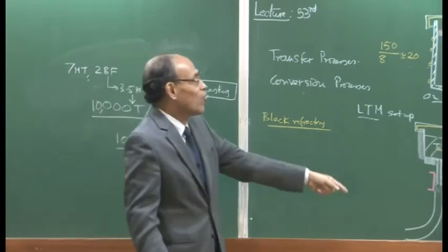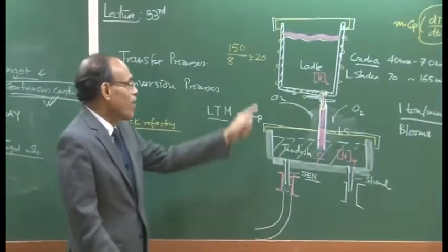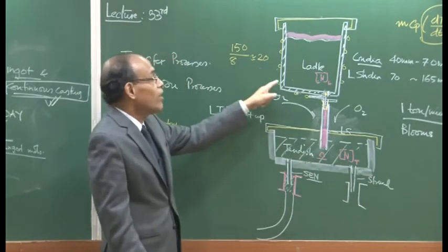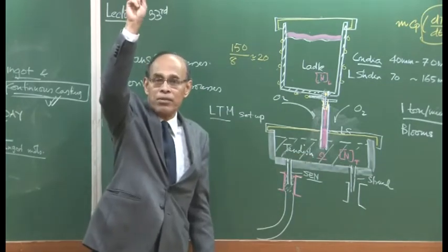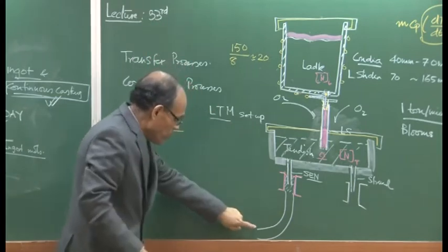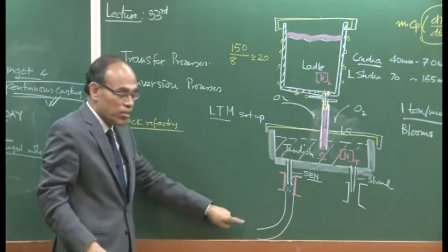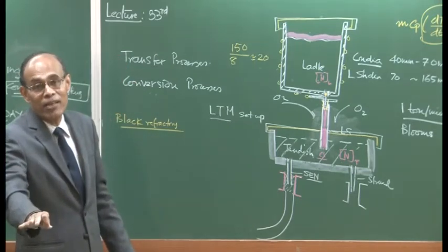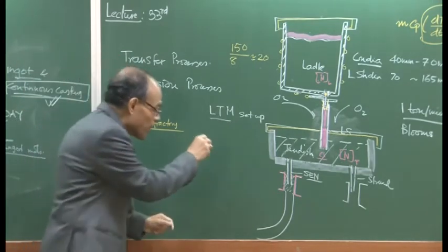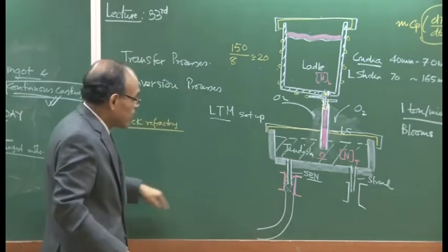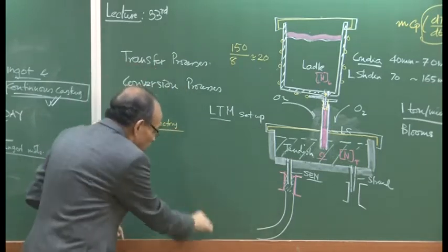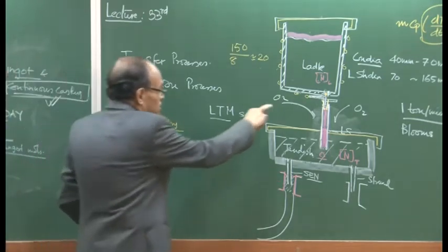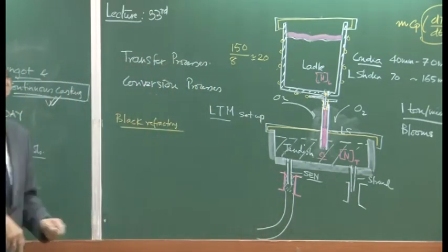And this is a typical continuous casting setup, where you will have a ladle sitting above the tundish, which will be sitting above the mold. The ladle will be somewhere about 3 floors up. The discharge of the continuous casting machine will be at the ground level, where you will be chopping this off, because it produces continuously, so you can imagine that it could have a length of about 30 or 40 meters.